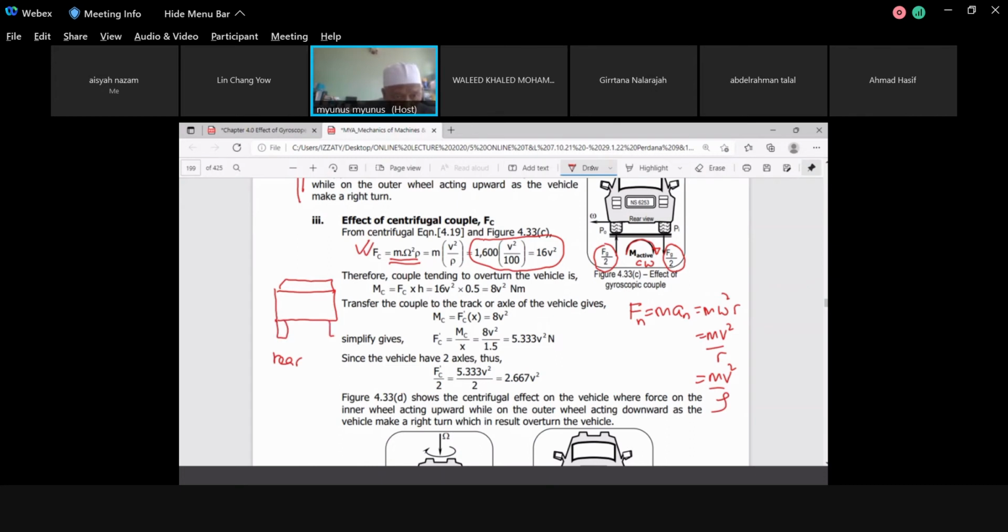It's a wheel. Center of gravity, and the center of gravity measured from the surface is h. And you will be calculating the F just now, which is, if you turn to left, pointing that way, turn to right, pointing that way. So this is the vehicle. This is your rho, always pointing inward of the curvature.